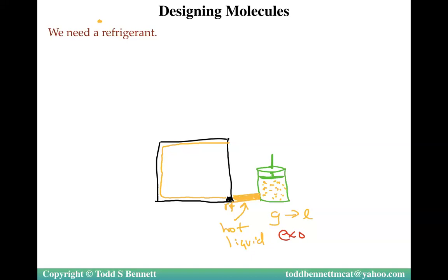And when it does that, you now have the liquid going back into a gas as soon as it enters here. So maybe it doesn't evaporate really quickly, so we have a kind of a slurry of liquid and gas. But then, as it goes through, it turns into a true gas. Going from a liquid to a gas is an endothermic process, which means it starts sucking up heat from wherever it can. The only spot to get heat is from inside the chamber. So the heat starts being sucked into the chamber walls, where it can be used to convert the liquid into a gas. Evaporation, endothermic process, as you perhaps have known, when you sweat and that water evaporates away, it sucks heat out of you. So as this liquid turns into a gas, as it evaporates, heat sucked in. And so finally what I can do is I can send this gas back into the chamber.